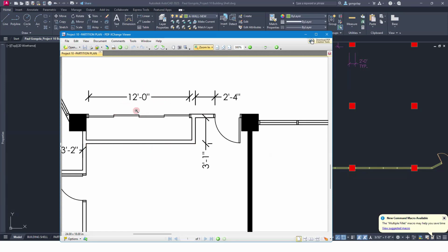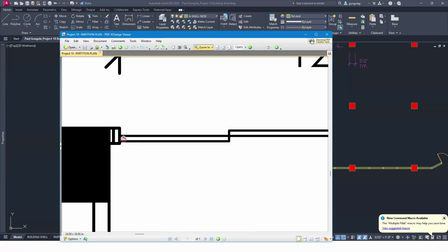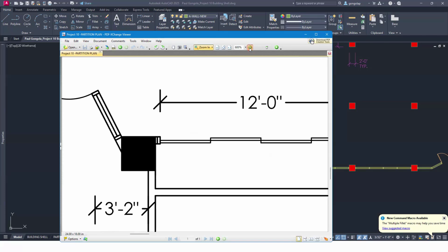Now this 12 feet, this is not the width of the closet. This is the width of this door opening. So these are four 3-foot doors. 3, 6, 9, 12. And when I'm drawing closet doors, I normally will make them 1.5 inches thick. So you can just use the rectangle tool or however you want to do it. But each one of these doors should be 3 feet long by 1.5 inches thick. And they should go on the proper layer. They should go on the doors layer.